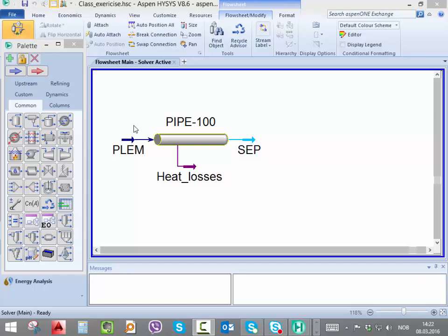So we were on our exercise. The exercise was the pipeline that goes from the Snohvit field, carrying the production of gas with some liquid. This liquid is partly water that was saturated in the gas at reservoir conditions, and when you take it up and the temperature begins to reduce, then the water carrying capacity of the gas also begins to reduce.